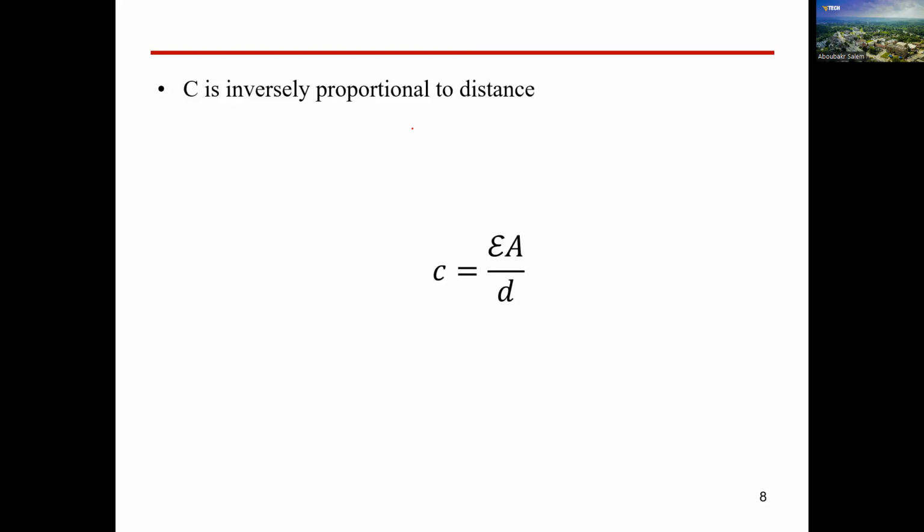So we have the two cases now. Let's start with the forward bias. In case of forward bias, this is the PN junction, this is P, this is N. So connect P to the positive supply, connect N to the negative supply. This is the forward biasing. So forward biasing means the positive charge here will be opposed to the positive or hole charges here. So it will make the holes move in this direction.